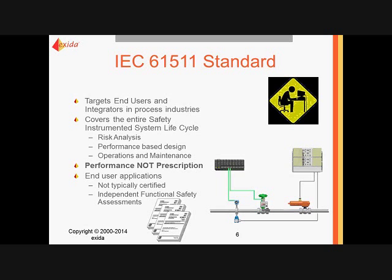And then you go into performance-based design, where you have your safety requirement specification that then determines what your safety instrumented system is going to look like in terms of the safety instrumented functions. How many of them are there? What are they there to protect against? And also what associated risk reductions are they going to achieve? And then you get into your operations and maintenance life cycle, where the system is running for its desired, what we call mission time. So again, performance not prescriptive.